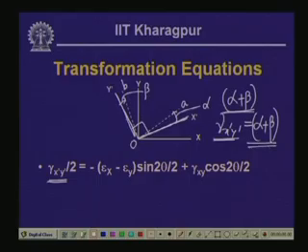Now, corresponding to the 3 changes that we have seen in case of plane strain, corresponding to stretching in the x direction, stretching in the y direction, and because of the shearing strain, the diagonal which is along the x dashed axis had undergone changes, the diagonal had changes in the angle, and those angles if we join them together we will get the final position of the diagonal.